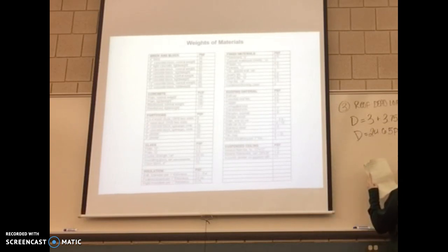And we're actually going to round up, right? We'd always rather design for a bigger load so our beam is stronger than not strong enough. So always round up to the next whole number. So I'm going to make a note. Always round up. Awesome. Put a big circle around it so this equals D. Perfect. And that is question 3.